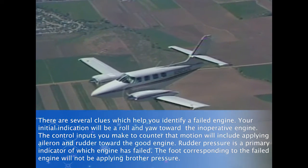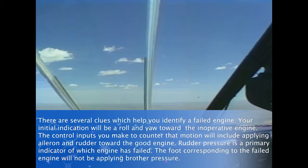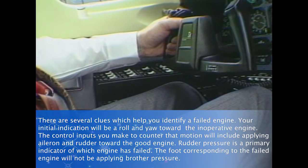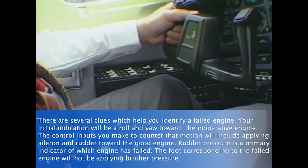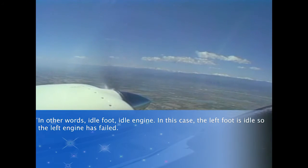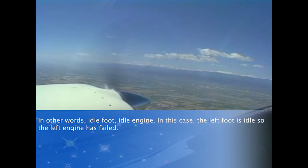There are several clues which help you identify a failed engine. Your initial indication will be a roll and yaw toward the inoperative engine. The control inputs you'll make to counter that motion will include applying aileron and rudder toward the good engine. Rudder pressure is a primary indicator of which engine has failed. The foot corresponding to the failed engine will not be applying rudder pressure. In other words, idle foot, idle engine. In this case, the left foot is idle, so the left engine has failed.